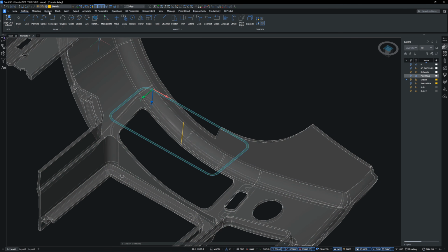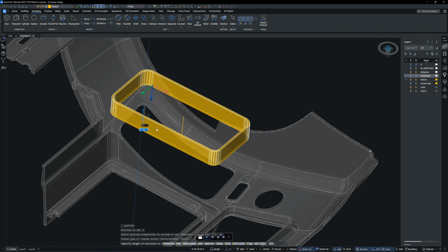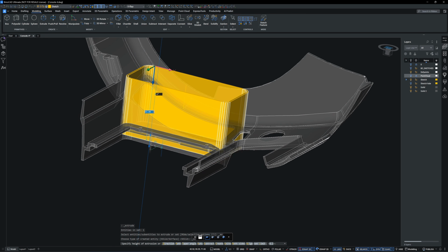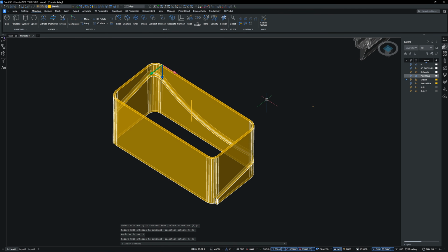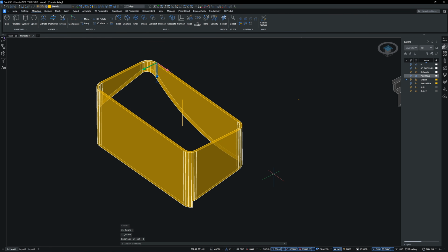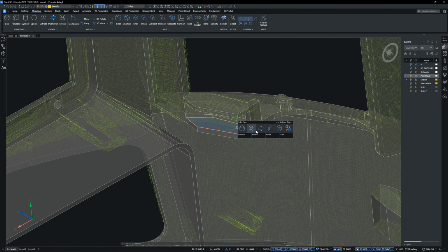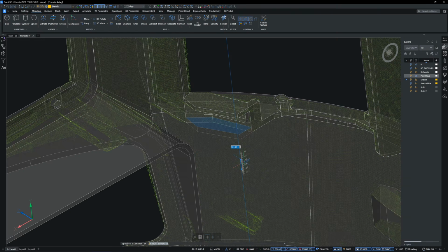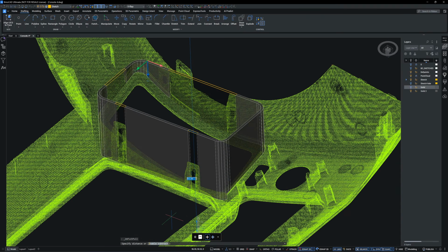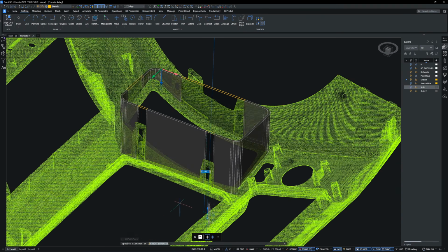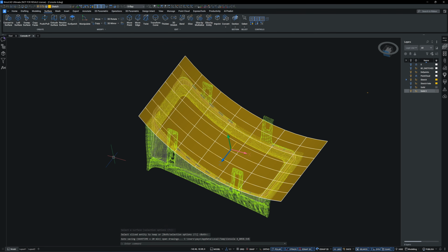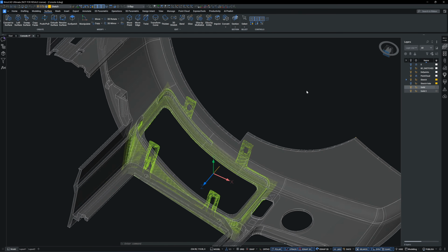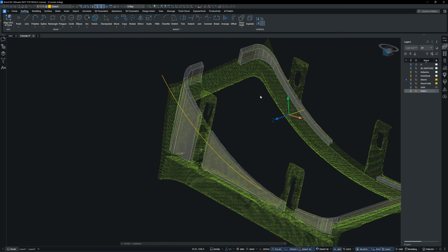This part is a bit tricky. It's the frame for the fan grill. I start by extruding it as a solid, then subtract it from the bezel. Here I notice a wall I missed and remove it. The fan grill pocket has 3D curved edges, so it needs to be trimmed with an extrude surface. I had to trim it twice to get the final shape.